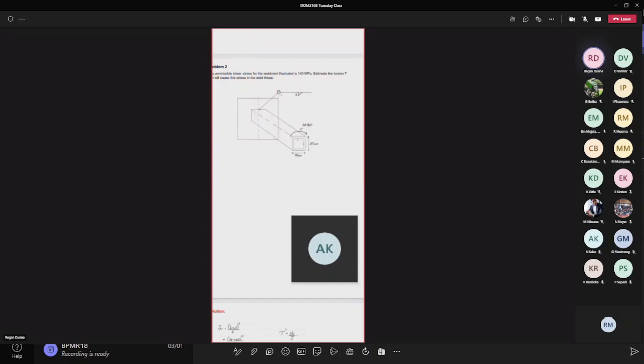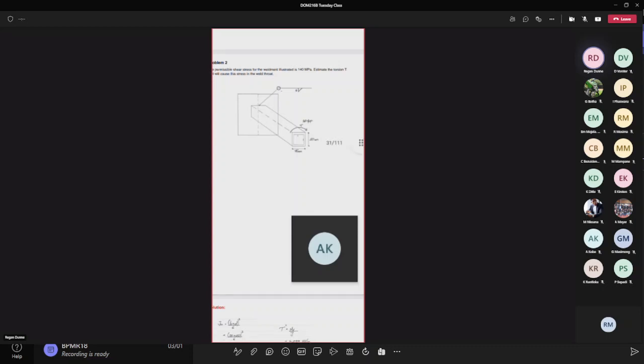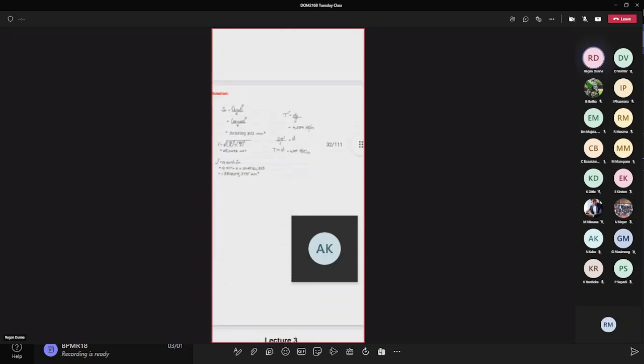So the weld looks like a square shape because the symbol shows that we have a fillet weld all the way around. Okay. So we go to table 9-1 and we then use the equations given to find the polar moment of inertia.